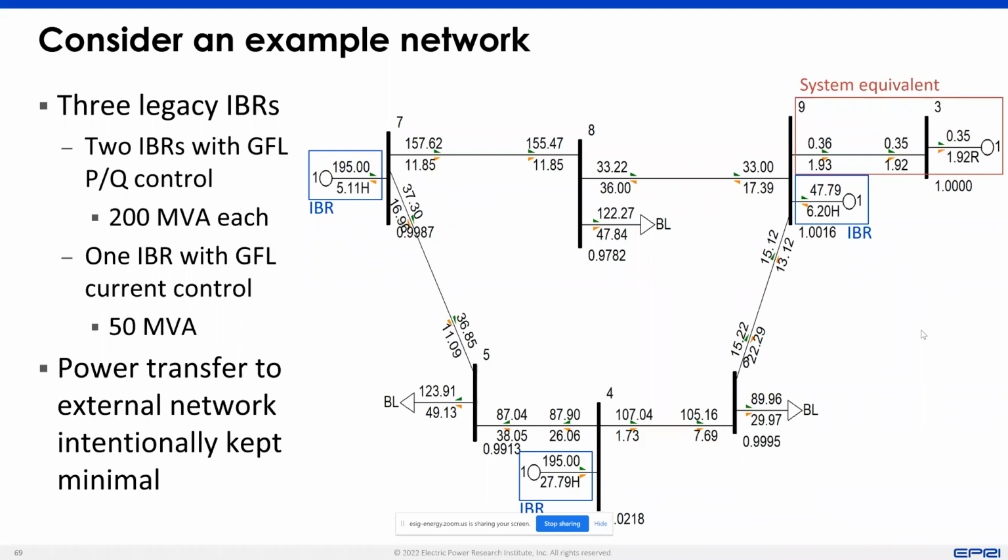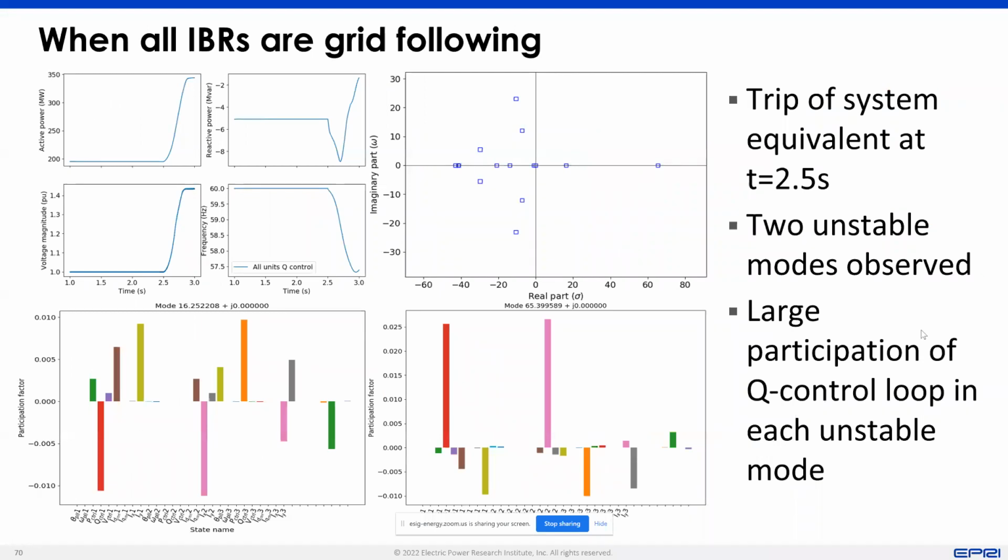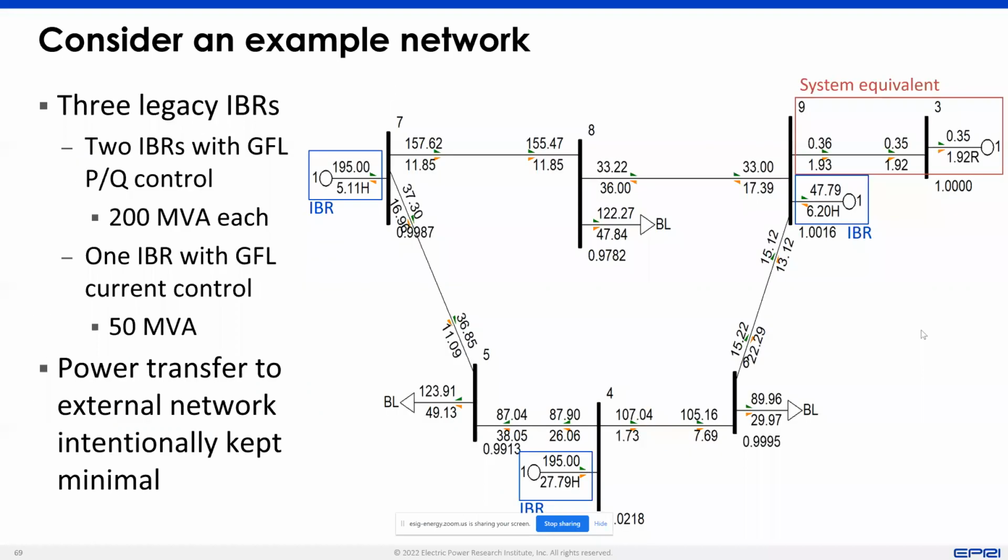It's around 1 megawatt, 2 megawatts, half a megawatt, 2 megawatts. But if now all of these inverters are grid following in characteristic, then you can create a small signal representation and really find out that all of these inverters will go unstable, or the system itself will go unstable, even for as small a disturbance as just half a megawatt and 2 megawatts, where one would think that maybe it will settle down, maybe it will settle to a new operating point and so on.